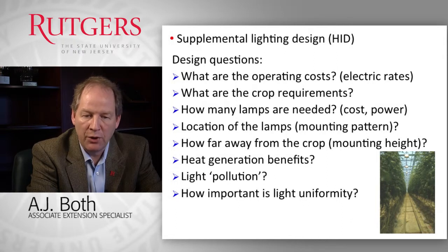Of course, you need to know what the crop requirements are. How much light does your crop require, and at what times of the day does it require that light? How many lamps are needed, because obviously that is going to determine the installation cost as well as the power consumption. Where can you put your lamps? So how much height do you have available between the lamp and the crop?